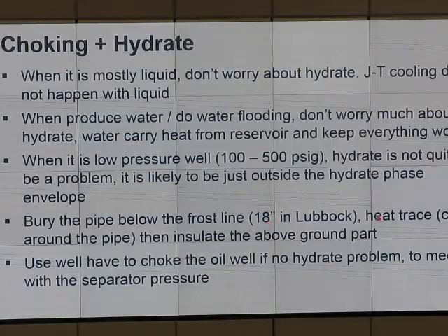If you bury the pipe, and the part that is above the ground, you use a coil, heat trace it, and then insulate it. Then you will be fine.